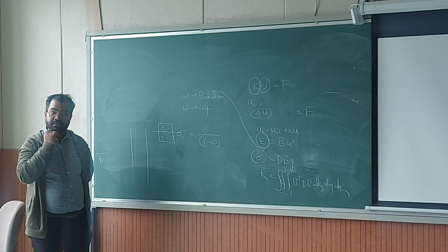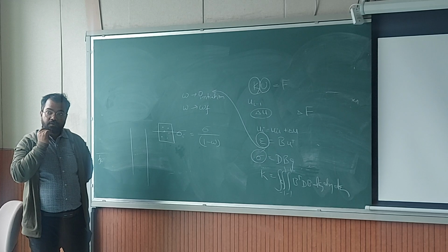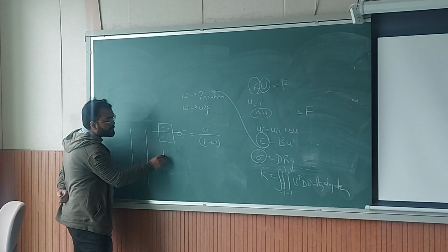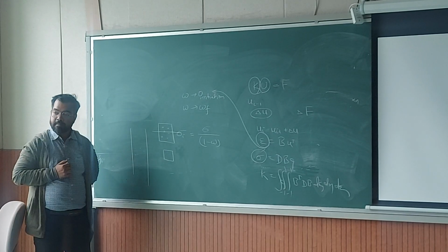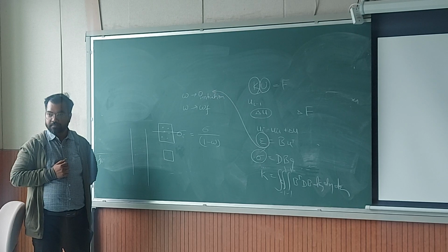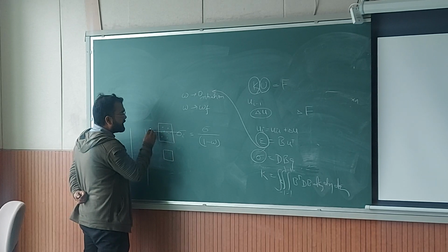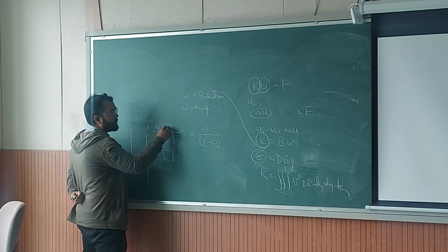This is what you are doing, right? So this is equalizing this to a smaller area element which has no void in it, isn't it? So because of voids, the real area is now decreased by the omega parameter.